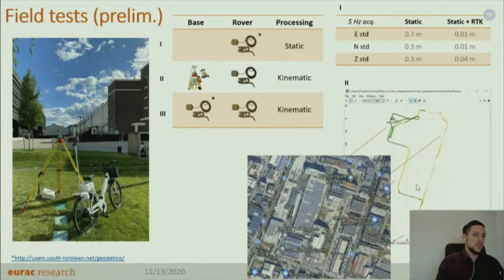This is something that we were expecting because, of course, within the urban scenario we have trees, we have side effects and wall effects, and a lot of reflection of the satellite signal from the walls. So of course it was expected. But what we were a little bit astonished and also proud to reach was that when we substituted this high-resolution GNSS antenna with another prototype, exactly the same one that was going around, we achieved 90% of fixed solution.